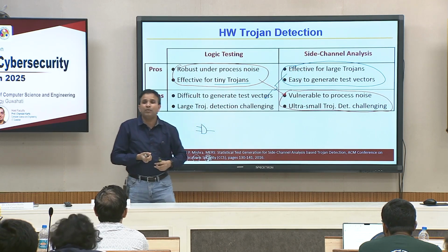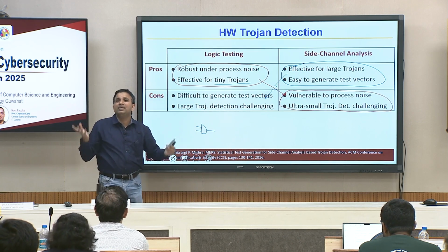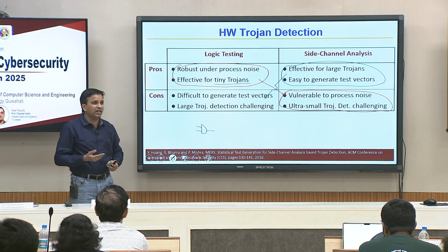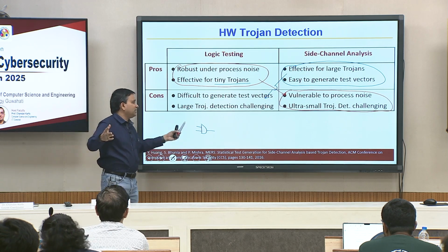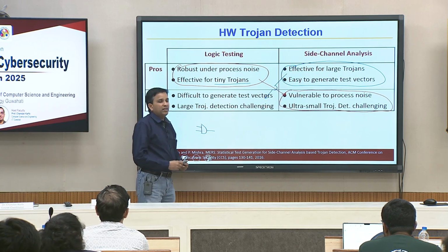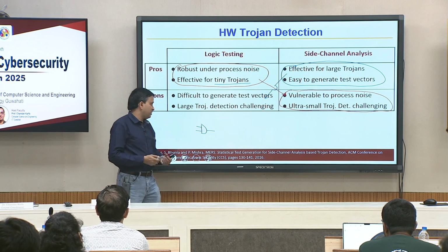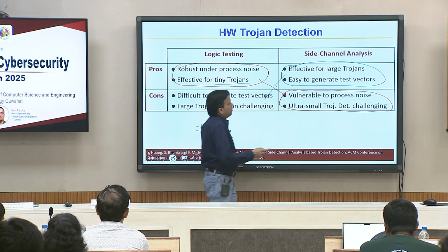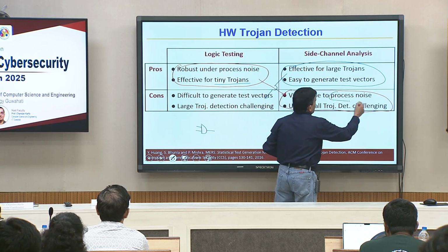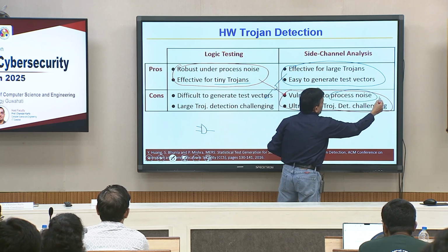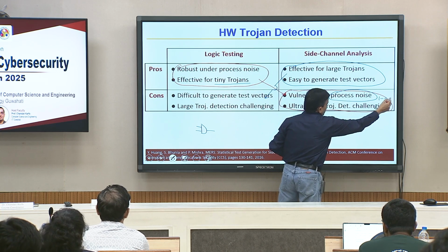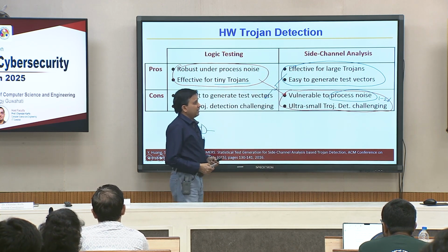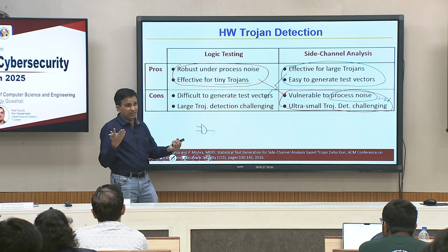In contrast, in side channel it is a negative problem, because for one tiny AND gate with 2 inputs, the extra power it would consume or dissipate is just negligible, not even nanowatt, even less than that. In a bigger scheme of things, when things are taking milliwatt or watt, a tiny nanowatt of power difference will not show up, specifically because of the process noise or process variation we talked about, that could be anywhere between 1 to 10%, let us just say 1 to 2%. That would still be in the milliwatt range. So, a nanowatt will hide easily.